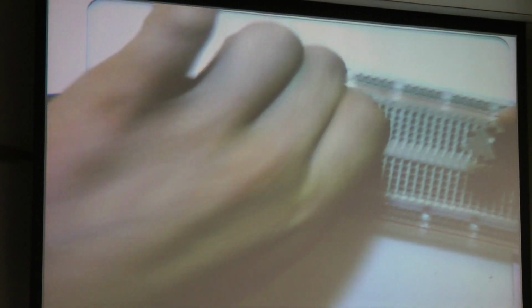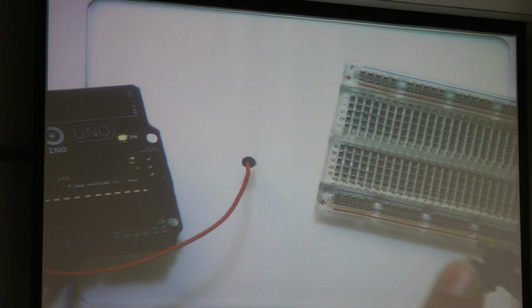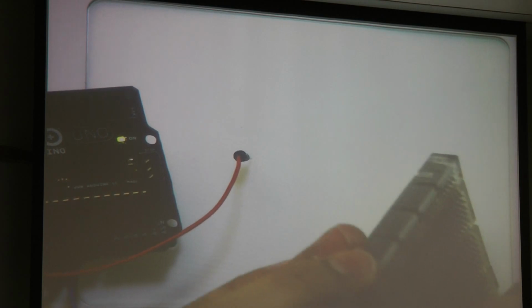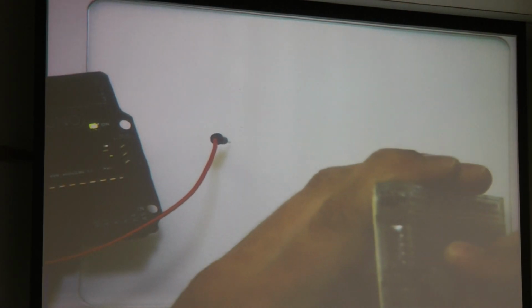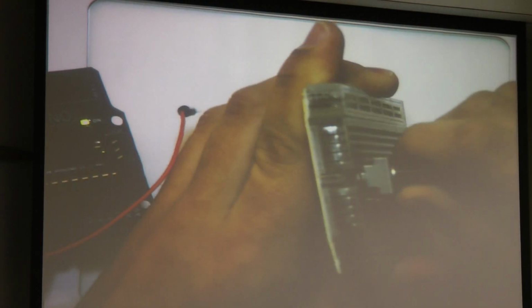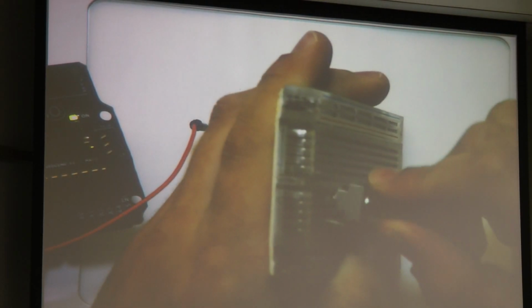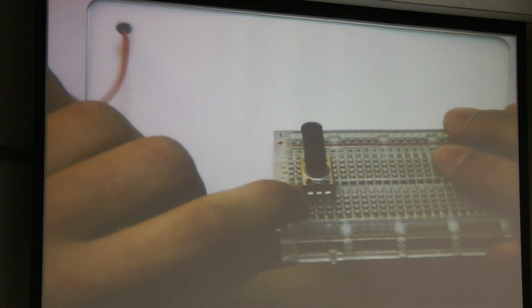So our potentiometer has these things that stick out here, and they're in our way. What we can do is, on the breadboard, if we stick it in the well, we can get it into the breadboard enough so it makes contact by pressing it on with these things in the well, because it's designed to be mounted in a PCB where you'd have a special footprint with holes. So we have that. On this we have 3 pins.